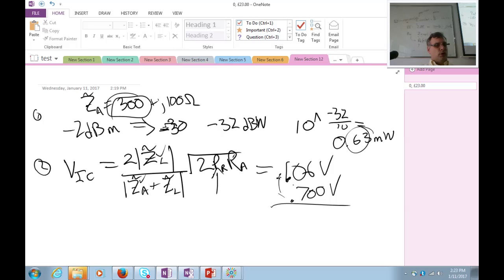It does. We would consider this to be fairly decent. It wouldn't be very high efficiency. You'd be lucky to get 50%. But we've got almost 400 millivolts above the turn-on threshold. The efficiency will probably be less than 50%, but we'll convert power.